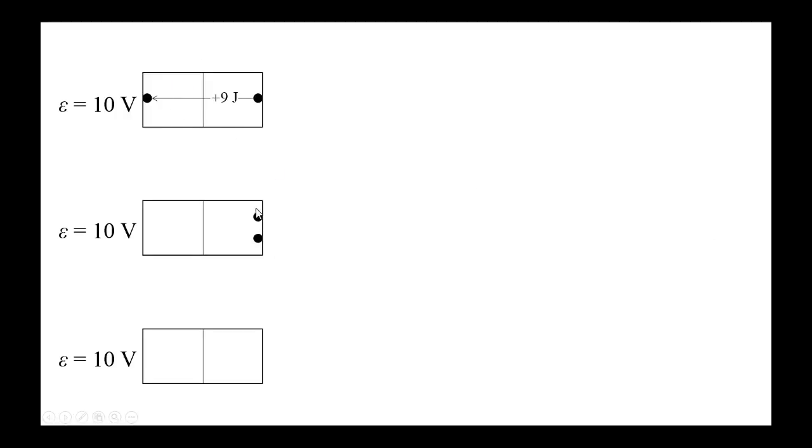So if we take 2 coulombs, or maybe a current of 2 amps, and we send it across, you don't get all 10 joules per coulomb. Each coulomb only gets 8. And if you take even more charges and you flow them through the battery, then for each coulomb, you do not get all 10 joules. Instead, each is getting only 7.